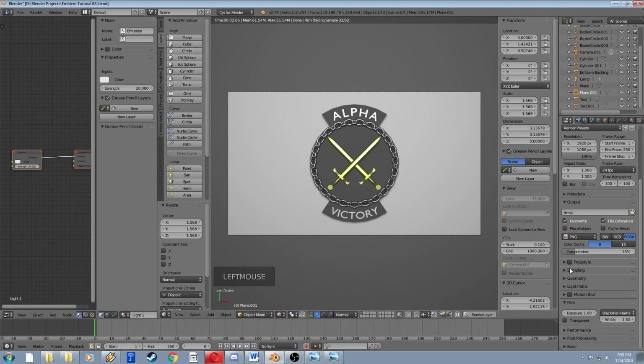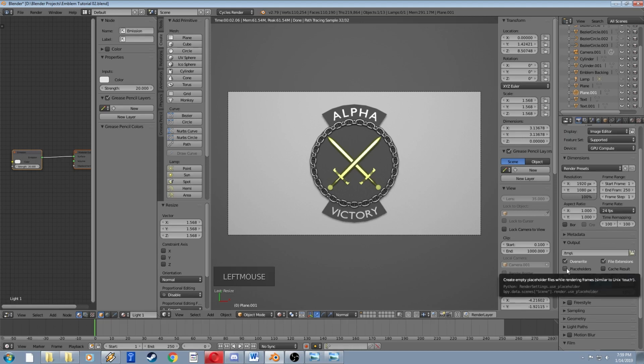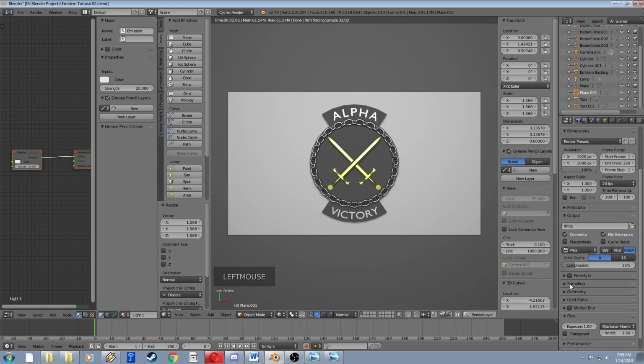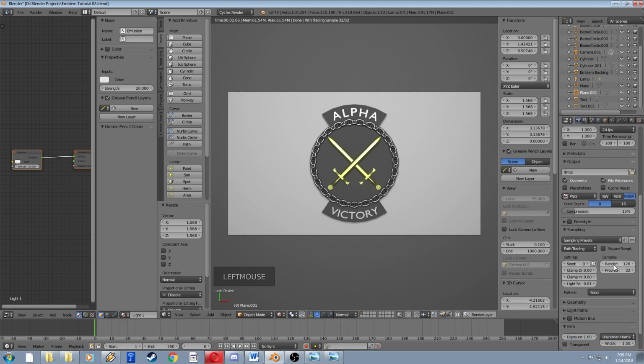The biggest thing for people who are new to Cycles in Blender is down here at the sampling tab. Right now, the render samples are set at the default of 128. In terms of Cycles samples, that's not a lot. So remember I talked about the static and the graininess of the image at the beginning?